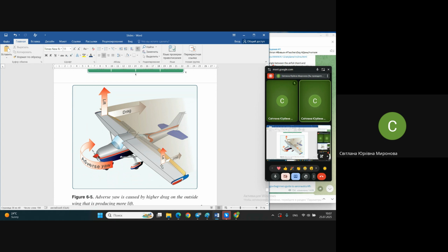But also, what we did here, besides reducing the lift? We increased the drag. Really, we spoiled the shape of the wing in this place, and quite clearly in this place we increased the drag due to this.